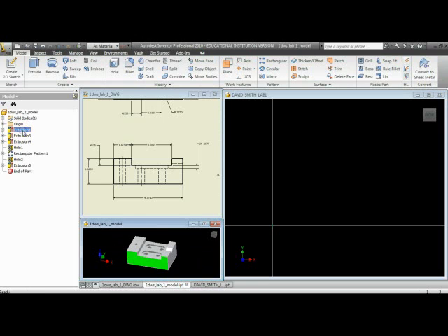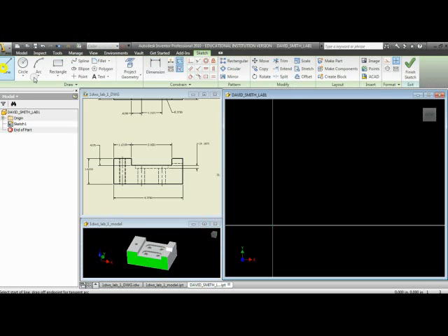Okay, the first thing we have to do is decide on this model, how do we want to create the part? I'm suggesting to you that we have to go in here and draw this shape first. We're going to draw that shape, and then we're going to extrude that back. And you can see that's what's going on here. So we want to catch this face first. So we're going to draw on that front plane, and we're going to draw some lines.